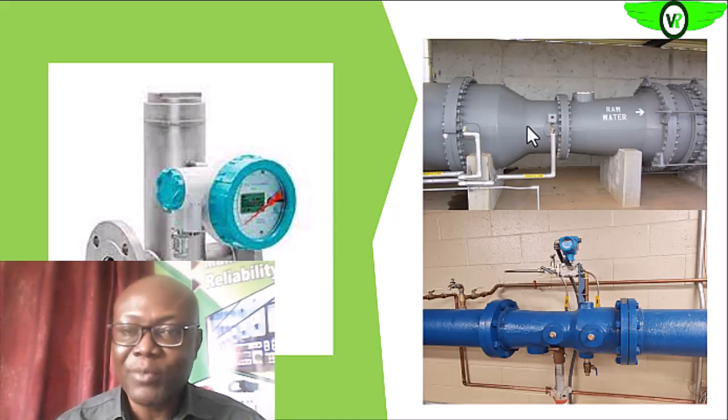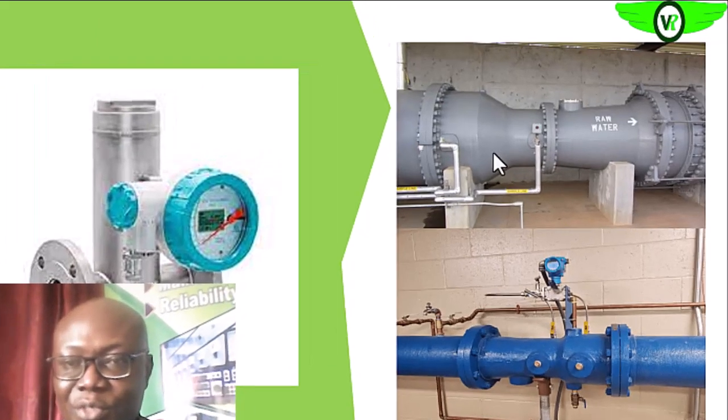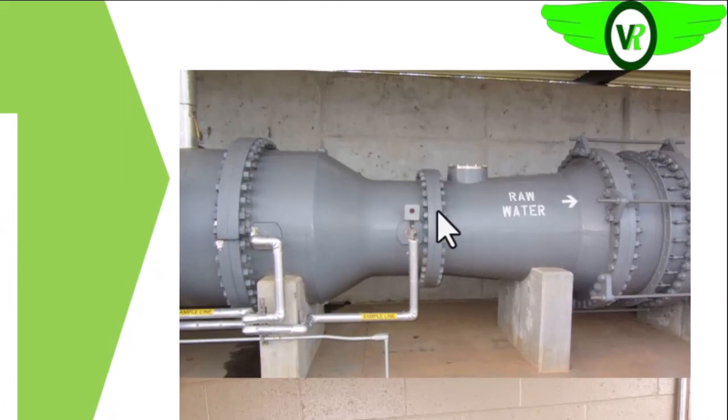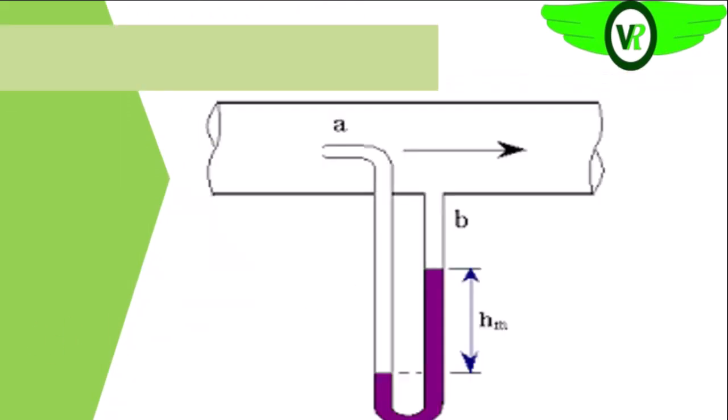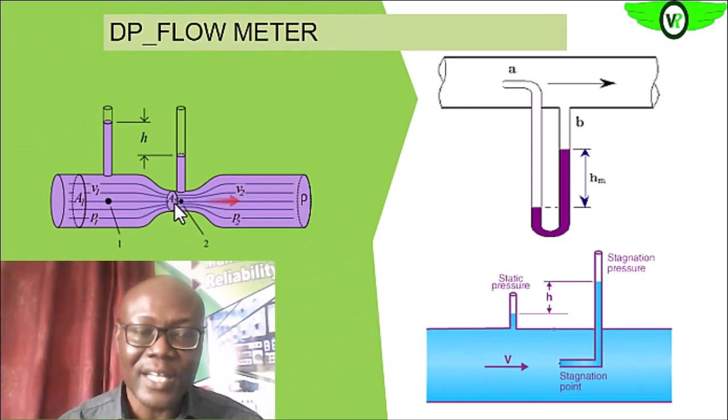So this is an example of a venturi tube. You see the tapered end. Remember, our goal is to create a restriction on the flow. As you do that, the flow velocity will momentarily reduce. That will make pressure want to go up, which is indicated on this leg of the impulse line.